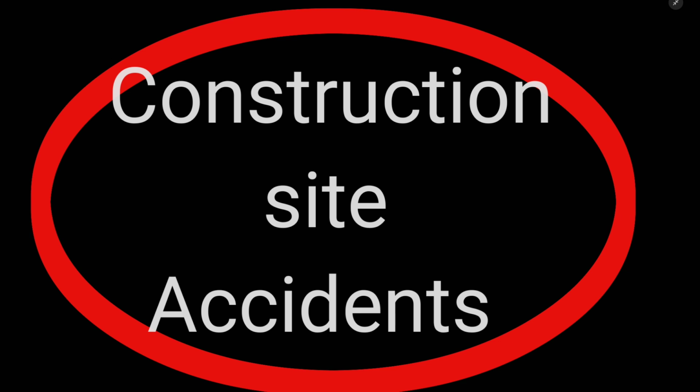Tenth is noise induced hearing loss. Construction sites are often noisy, and prolonged exposure to loud machinery can cause permanent hearing damage. To prevent this, workers must wear earplugs or ear muffs when working with loud equipment, and noise levels should be monitored.